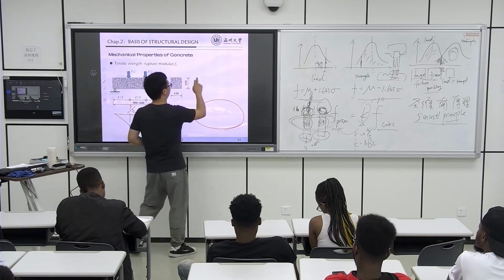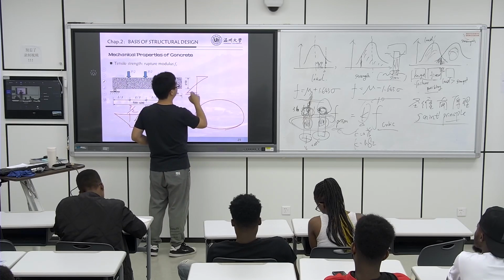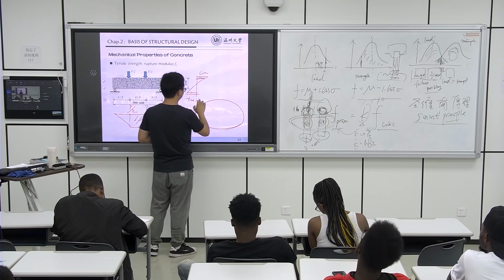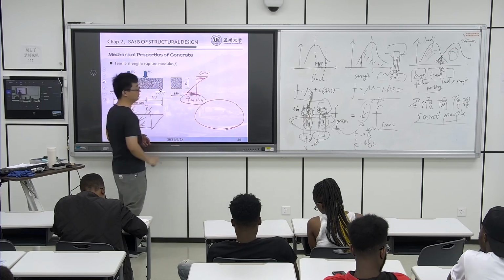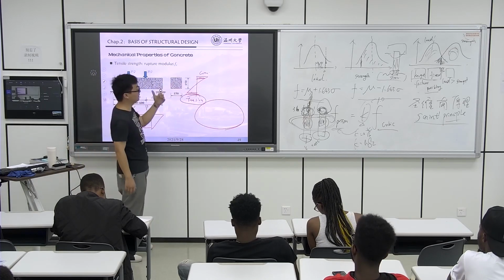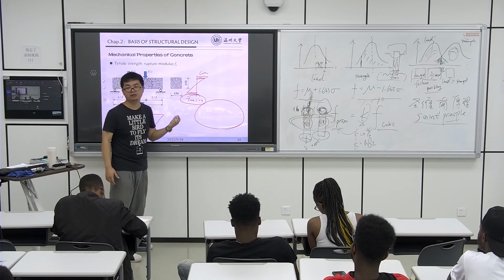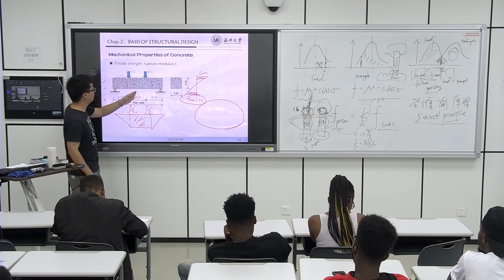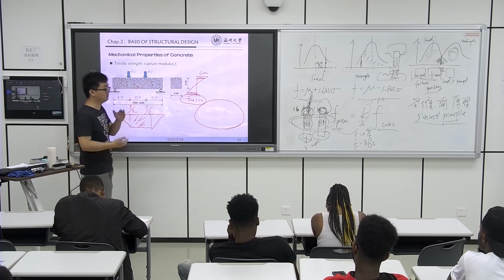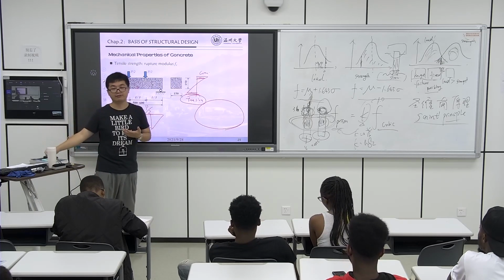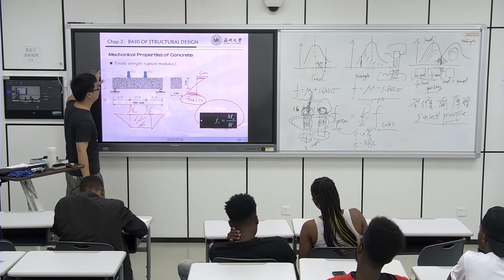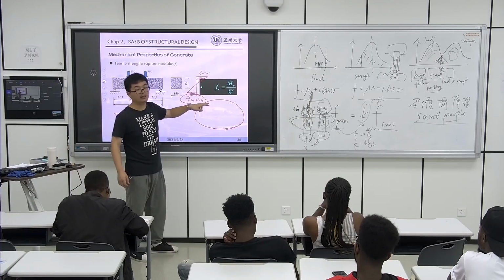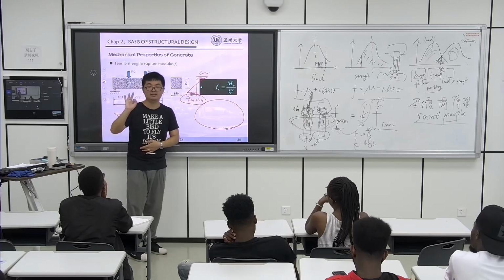And in the section, the stress, this here is the compression, right? And this is the tension, right? So from this test, we also can compare the tension strength. We give the load, and if a crack happens, we stop and write down the values, and then according to this formula we know the tension strength.